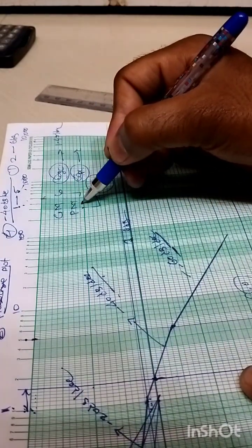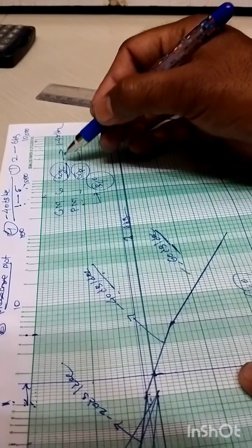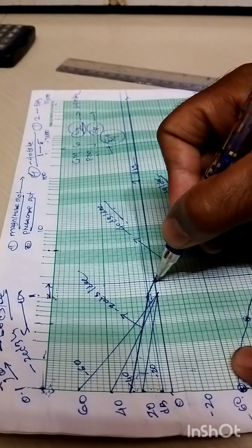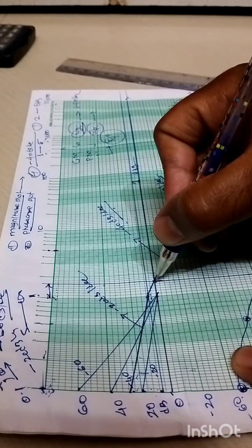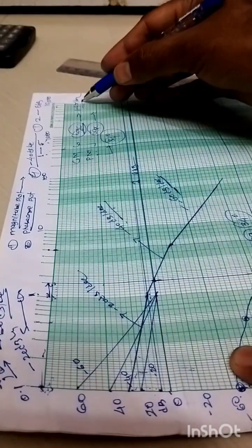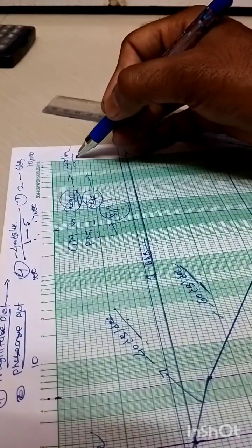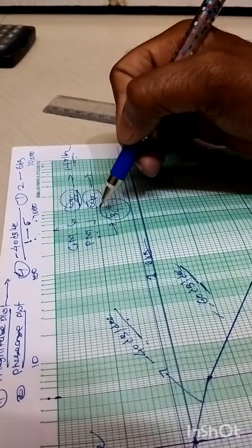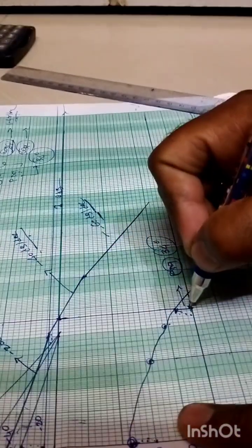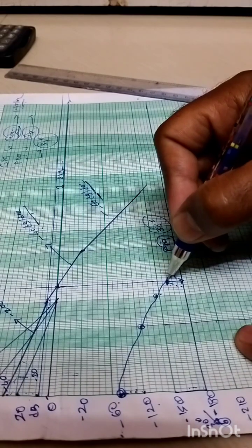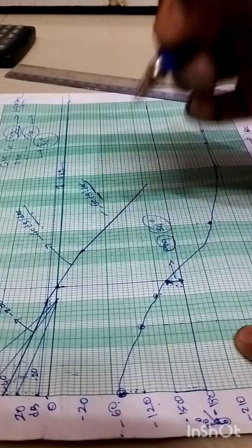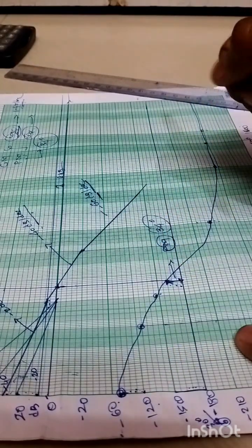In order to determine phase margin, we have tabulated the gain crossover frequency, as far as this magnitude plot is concerned, so the desired frequency at which magnitude equals 0. So this frequency is how much? It is 1.4 radian per second. This gain crossover frequency is used to determine the phase margin, right? So this gain crossover frequency is being projected on this magnitude plot and it will intersect here, and so we need to determine that particular distance in this phase angle plot.